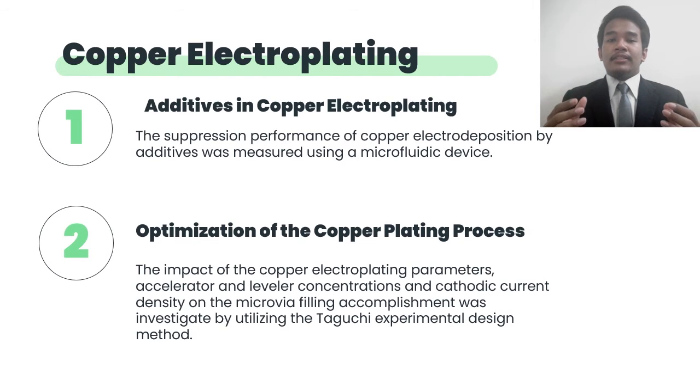Throughout the electroplating, the supply of additive was interfered with by exchanging the plating solution in the microfluidic device, and the activation of additive was monitored clearly. Optical microscope images revealed the appearance of numerous protrusions after the leveler had been interfered with.